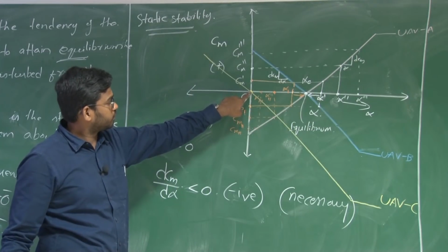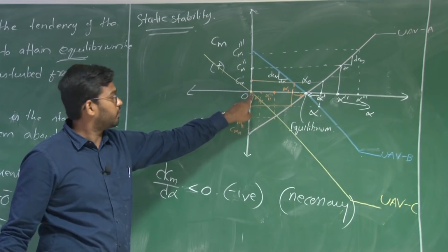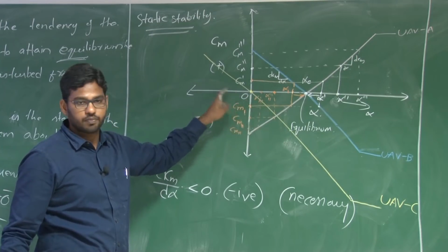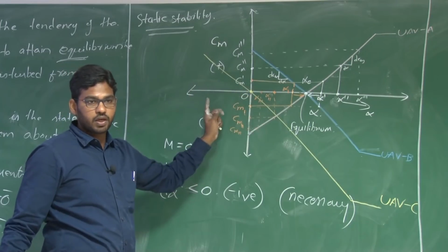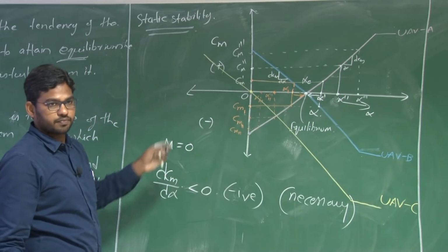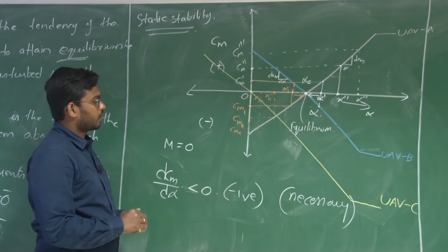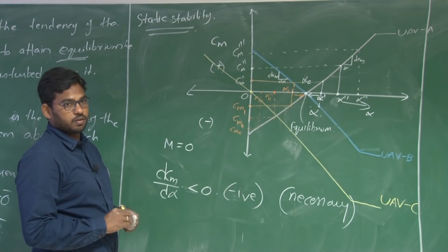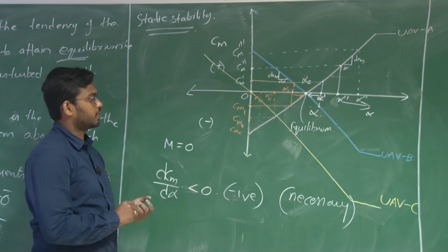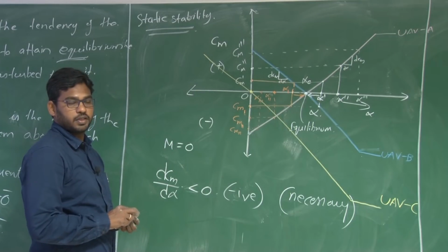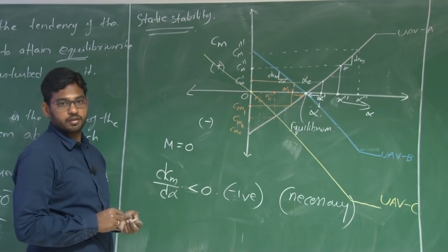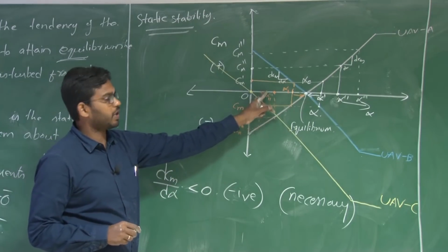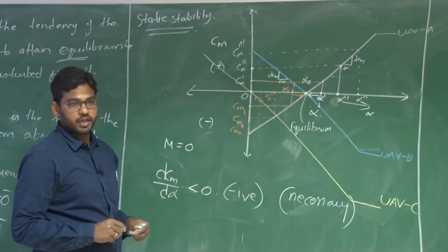So about this equilibrium, when there is an increase in the angle of attack, there is a nose down moment that will take you back towards your equilibrium, and vice versa. But what is the trim for this UAV? It is at 0 angle of attack, because you can't trim at positive angle of attack, you will get negative moment.